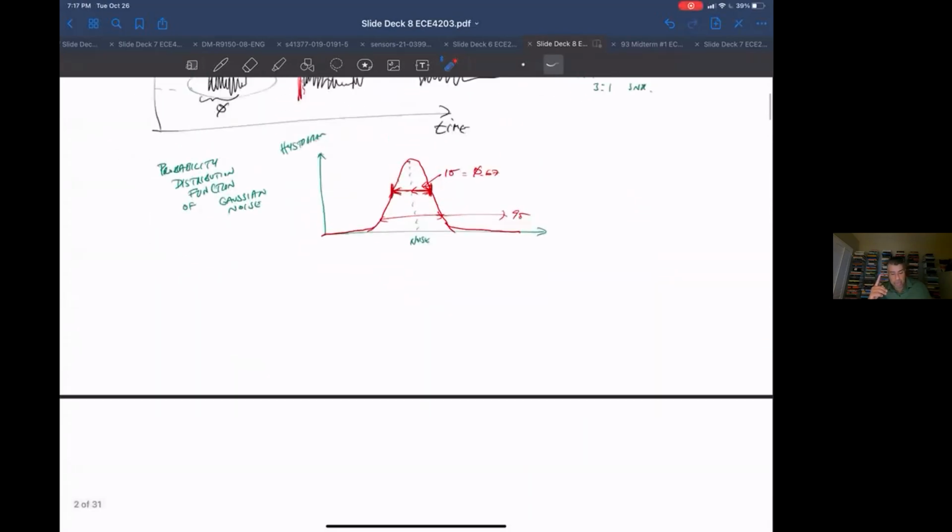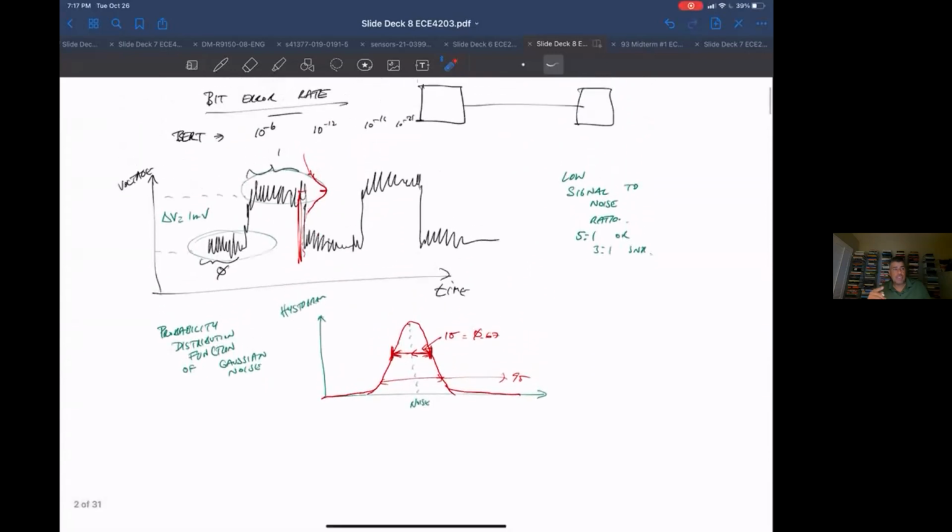But there's a difference between stuff you do on a chip or in your FPGA or microprocessor and an internet, Ethernet communication channel or a wireless communication channel. Typically, especially inside the chip, you really don't have any error correction. So if any error does come in, you're typically not doing CRCs or anything. Your adder, your multiplier, your processor, your memory access, all that's happening, and there's no correction. If you make a mistake, it'll just be a mistake.